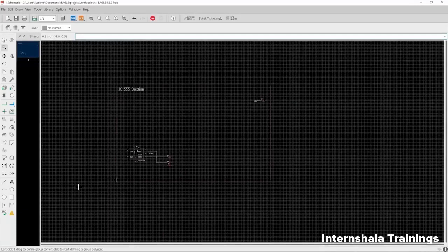Okay. After that, this arc option, then this polygon option is actually not that important. After that, the most important option is ERC, okay, which stands for electrical rule check. Now, let's say that you are done with the schematic. You have created the schematic for all the different blocks which are present on your hardware. Now you have to verify whether there are any problems in your schematic or not. So the software is going to tell you what the errors and what the warnings are in your schematic.